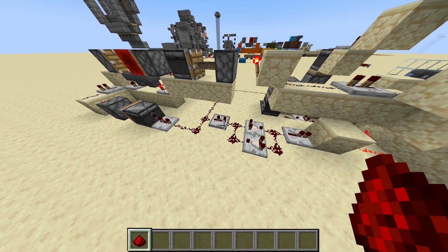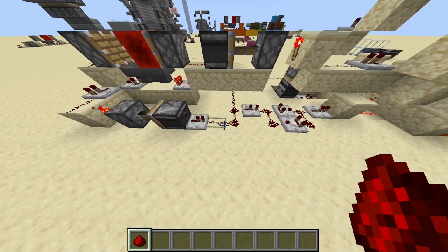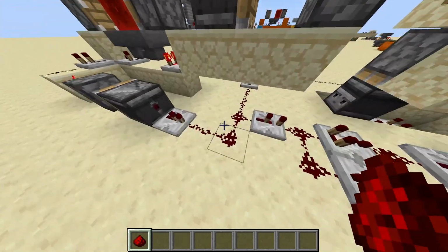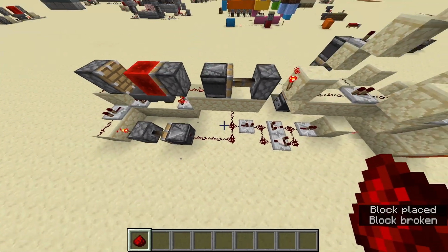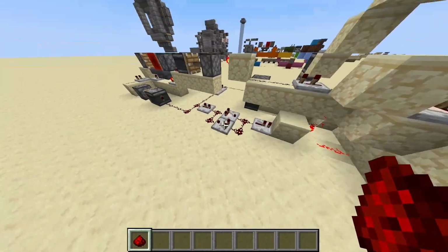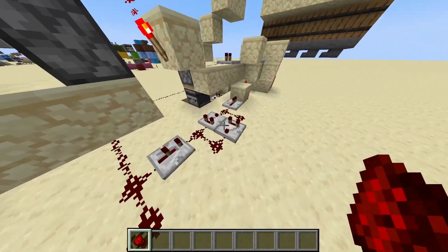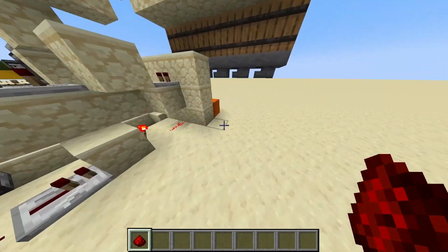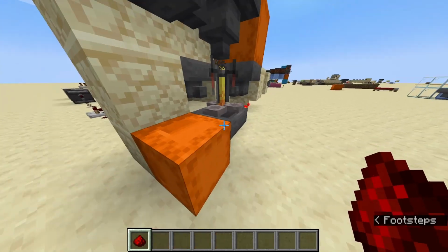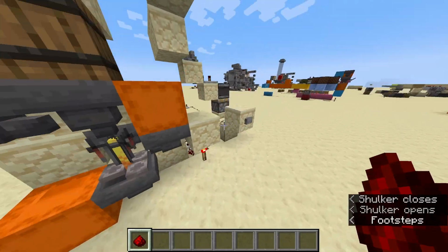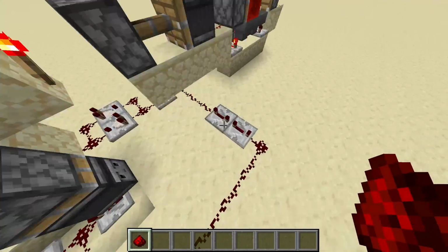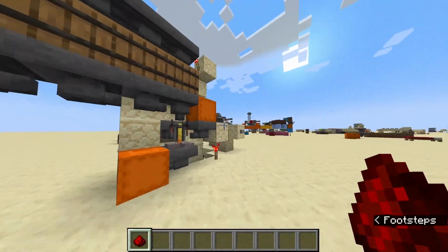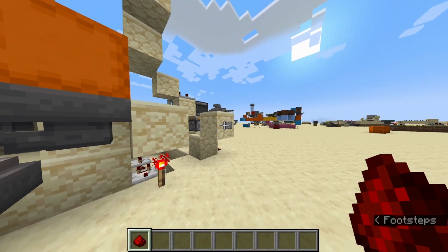Yeah, I see what I kind of forgot. So how long does this thing need to be on for? Just needs to be on long enough for that to work. So maybe if I get rid of that, because what's happened is this circuit has bled into here, so this monostable circuit is on for a lot longer than it needs to be. And that's why the items were leaking from here to here when they shouldn't. So I've also added a bit of a delay here just in case, but I might be able to remove that should that be the case. And now we'll do another rundown to see if this works properly.